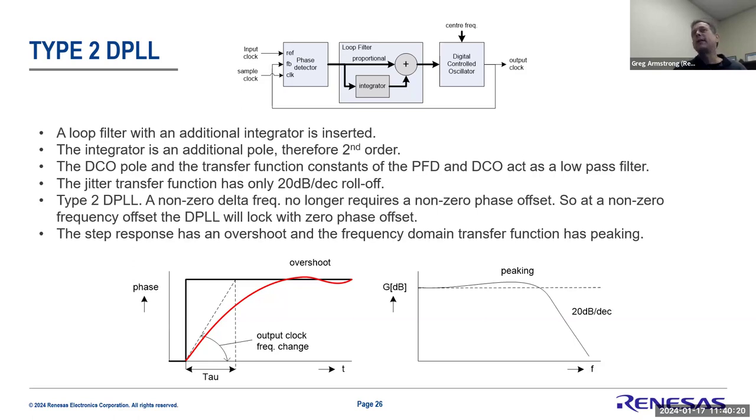The integrator basically takes that 10 and says, well, I'm going to do a very long-term average of that 10. And so if I continuously get 10, eventually I'm going to spit out 10 to the summator there, which means it gets summed to the proportional, and then that's the final value. And so this is how you see a very quick offset.